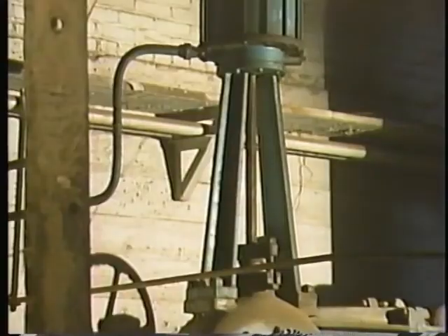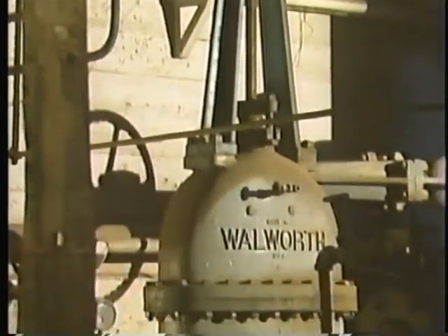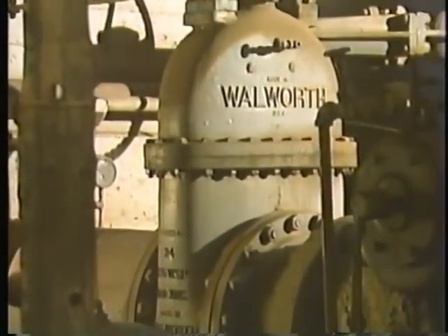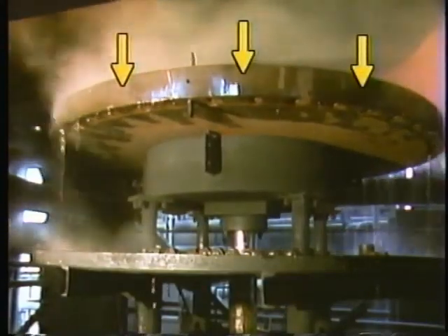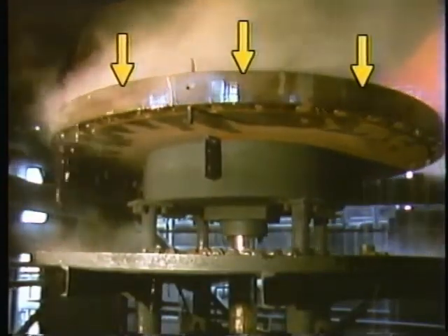For example, it may be necessary to operate an emergency system valve relatively quickly. On the other hand, a heavy load, like this one, may have to be moved quite slowly. Depending on the purposes of a hydraulic system, flow control valves may be used to control the flow of fluid to an actuator or from an actuator. We'll look at some different methods of accomplishing these tasks and why they're necessary.